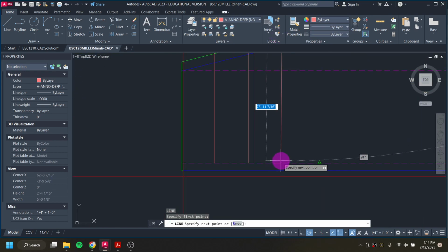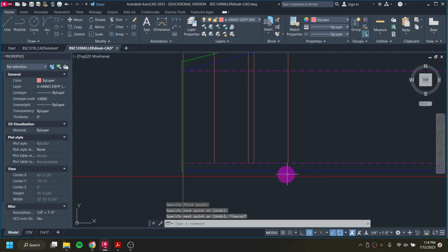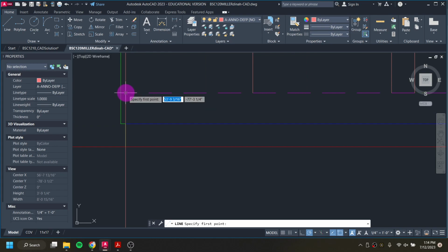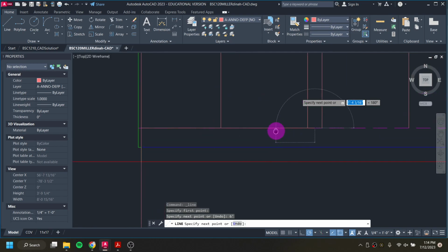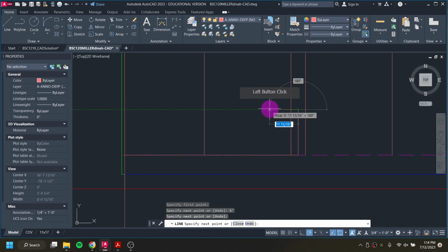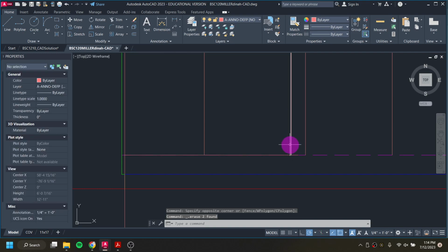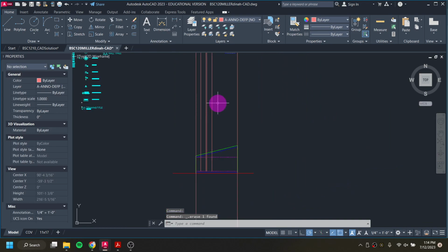I won't have to measure anything related to my porch. I absolutely could have taken a measurement. What I could have done was gone into the line tool, and from the face of my stud, which again would be here, I could have gone in 6 foot, and then I could have gone over 3 inches, and that would have gotten me in the exact same spot. But I find just projecting them straight down from my view is a little bit easier.